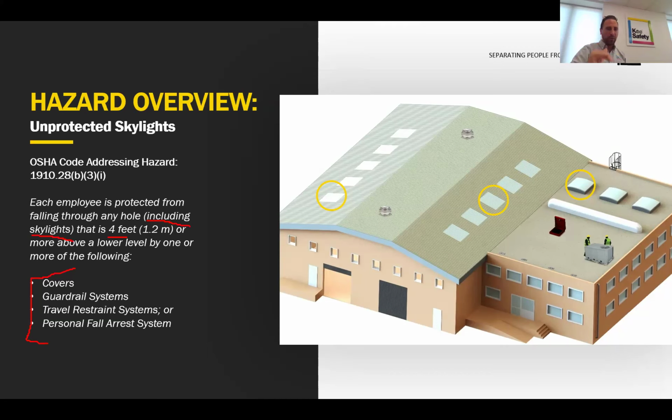So let's once again apply that knowledge to fall protection. Let's say this is the skylight that I need to try and protect right here. And let's say I'm tied off and I fall through it. Well, what am I going to hit on the way down? I don't know, because I don't know what my fall clearance is below that skylight. So fall arrest or active fall protection around skylights is super dangerous because we don't know what's below the skylight.